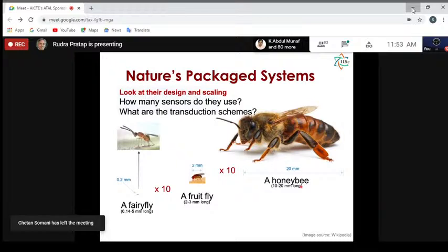So, if you think of a cantilever beam, it's like this. There is a cantilever beam. If you apply a load on it, it deflects, and the deflection delta is the load times length cubed divided by 3 times Young's modulus and the sectional inertia of this cross section.